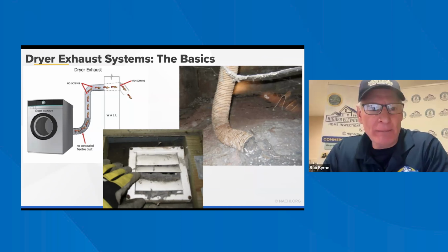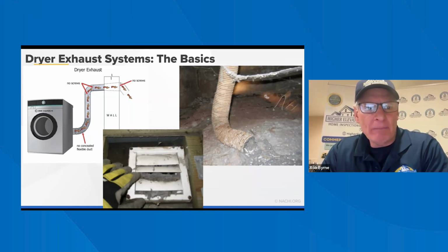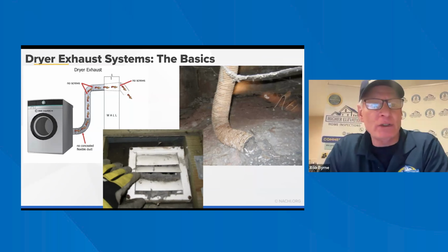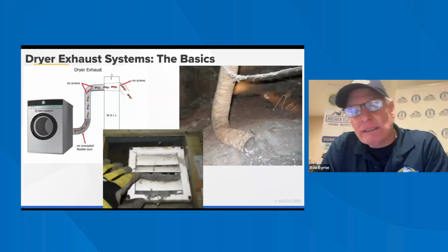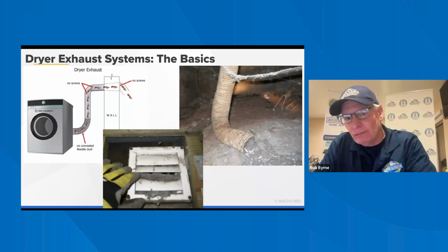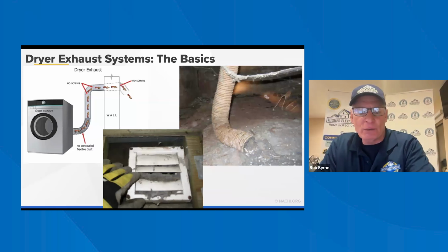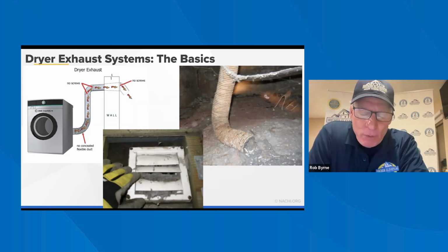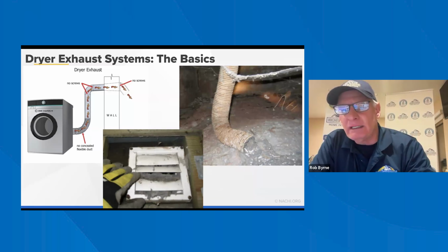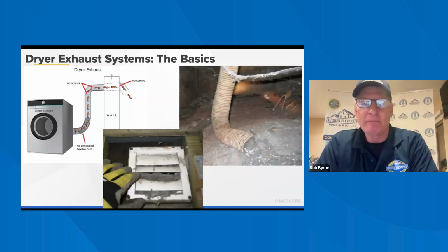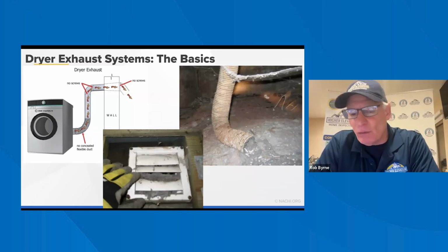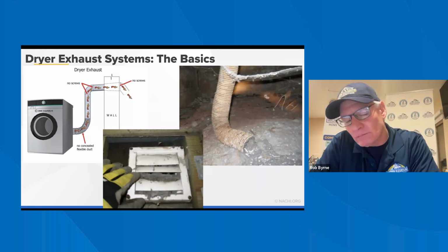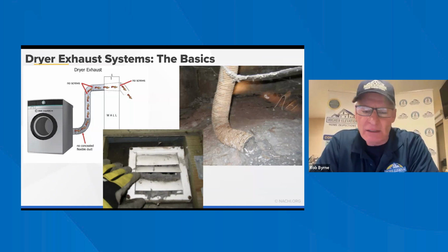Okay, so now, as the other part of the plumbing inspection, we talked about the appliances earlier. One of the areas of concentration you're going to do on the dryer is the exhaust vent. You never want to see a dryer vent discharging into a crawl space like you see here. You also want to make sure that the vent is not clogged, and you get flow. What most people fail to understand is that this lint from the dryer is highly flammable. So if it's in the basement or in the crawl space, it's a potential fire hazard. So whenever we see this, always call it out and get it corrected.